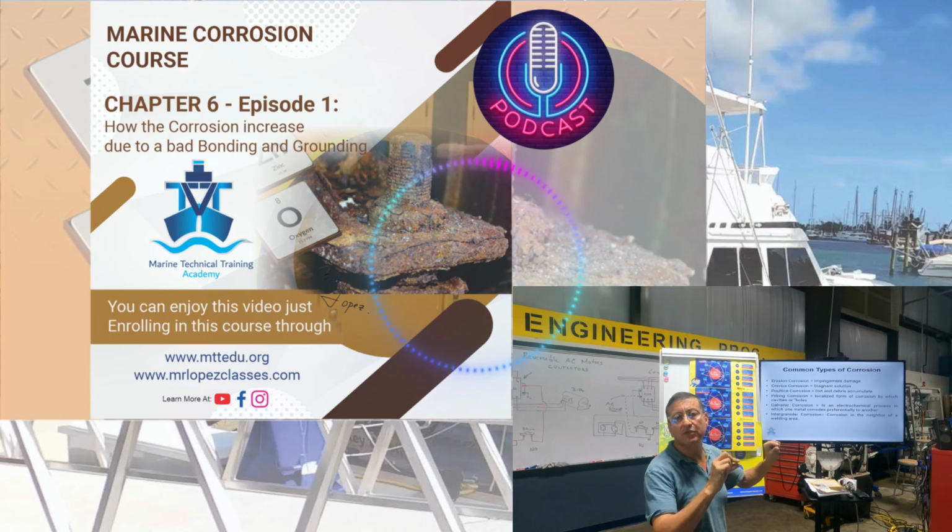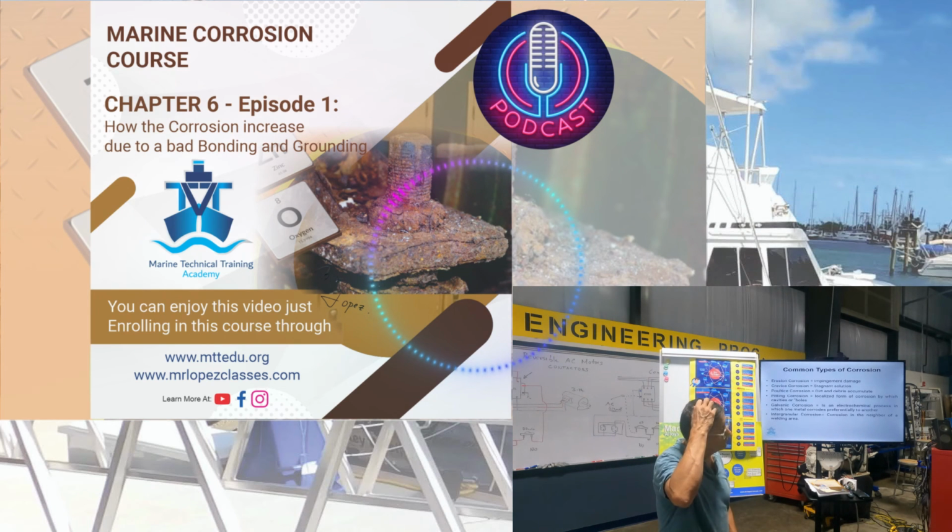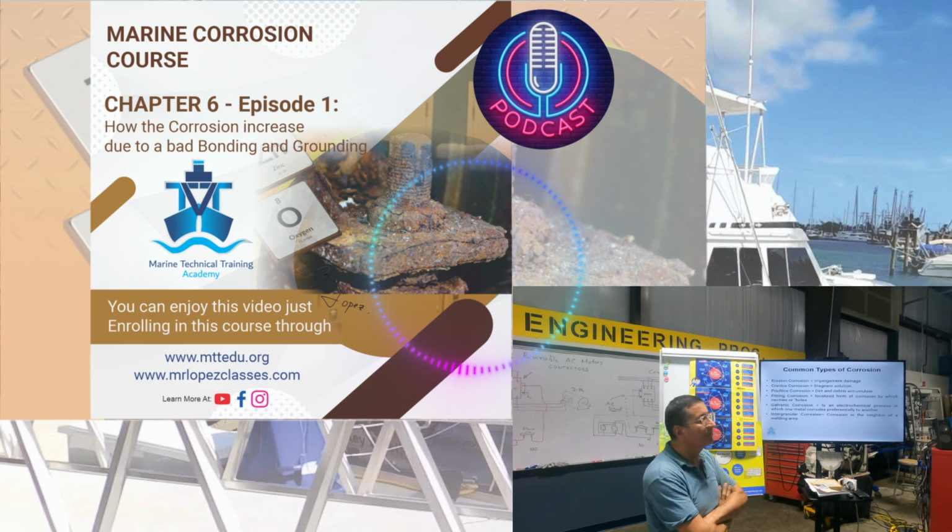The isolator transformer, by induction, creates a new signal that is completely clean. If you remember, this is the picture for the isolator transformer. The signal is contaminated in the input, and in the output the signal is completely clean. Where is it located? This is the shore power entering the boat, or the power from the generator, passing through the switch selector, you select generator or shore power, and from the common you insert the isolator transformer in series, hotline and neutral, and the output is the clean signal.